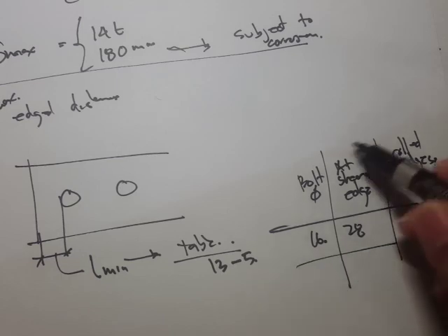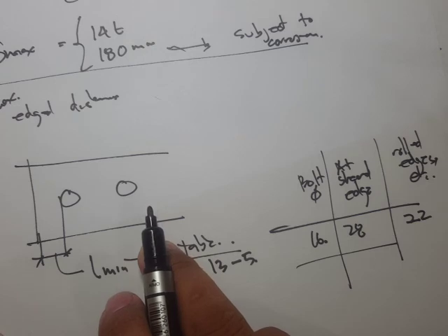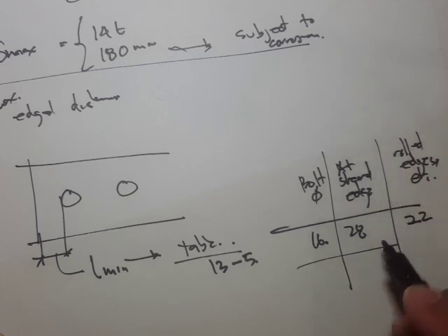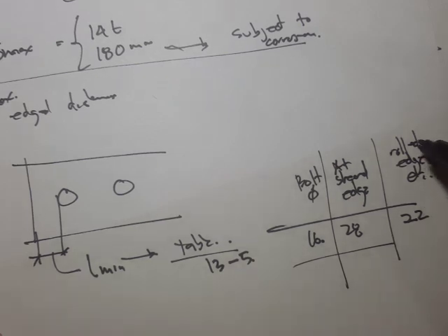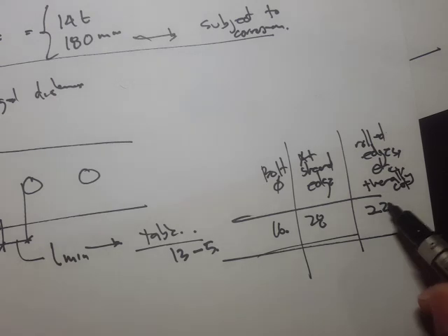So at sheared edges, if this material is being cut using shearing action, then that's going to be this. But if it is cut thermally, let's say using acetylene tools, there's rolled edges and some details here. It says thermally cut. So the value of the minimum is 22.